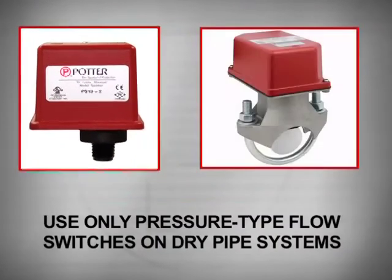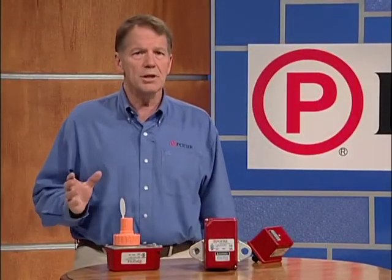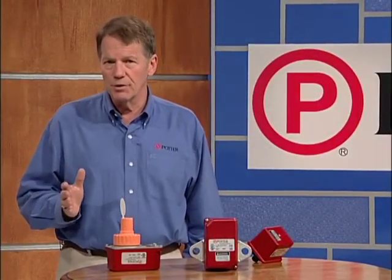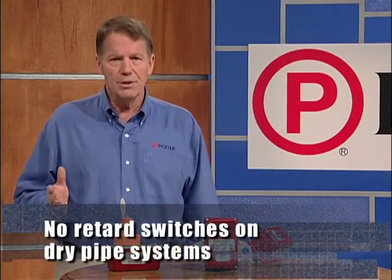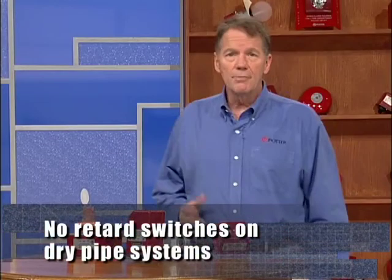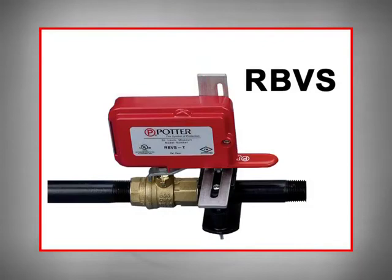Vane-type water flow switches are not allowed on dry pipe sprinkler systems. When a dry pipe valve opens, the water rushes in with such force that the vane-type water flow switch could be damaged. There's no need for a retard or a retard chamber on dry pipe systems. In fact, retards are not allowed. If there's a shutoff valve between the dry pipe valve and the pressure switch, the valve must be supervised with the Potter RBVS. The Potter RBVS is a tamper switch used for monitoring the open position of a ball valve.